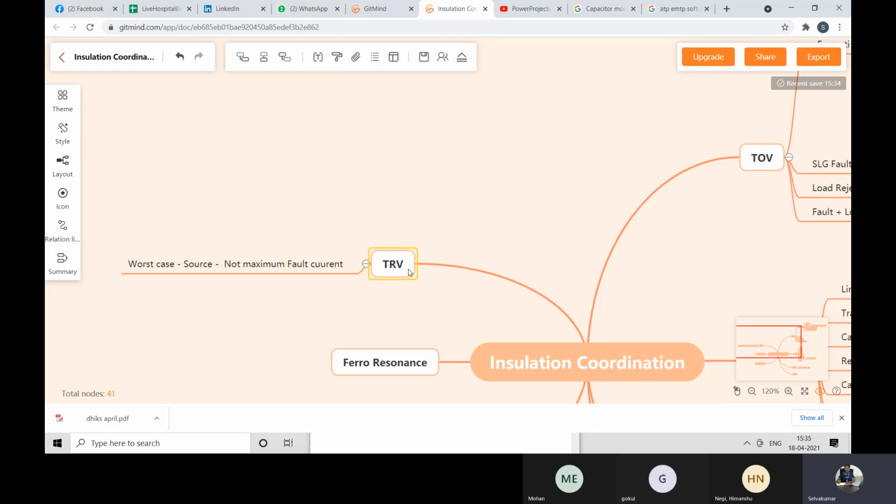and your equipment has a capability to withstand, that is a short time withstand rating, and your breaker has a withstand and breaking capability for that fault current. So that is both current. It can be maximum 3-phase and maximum single phase.